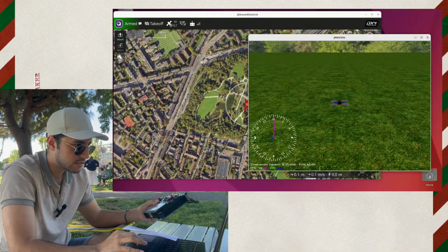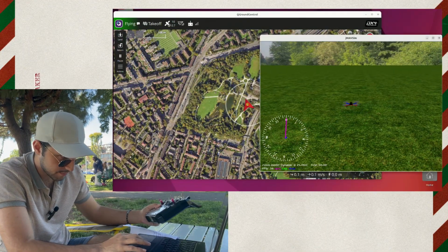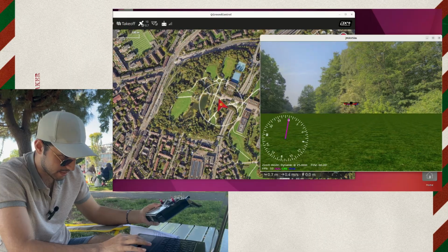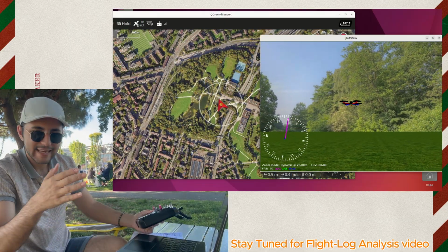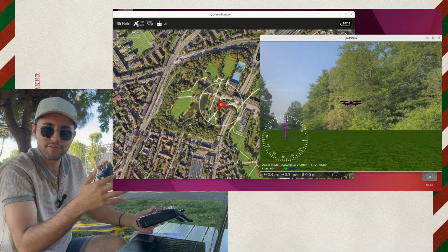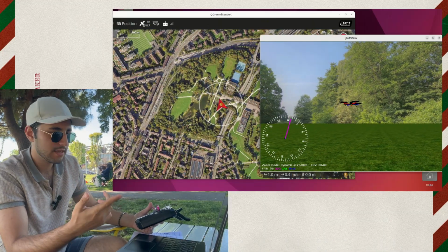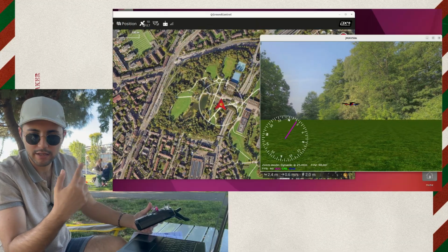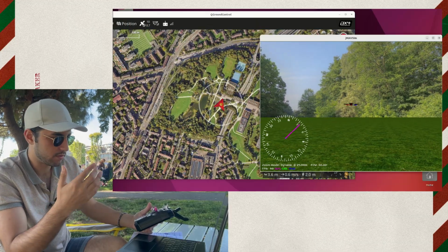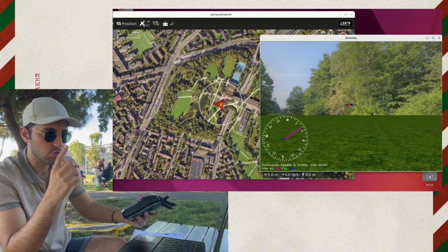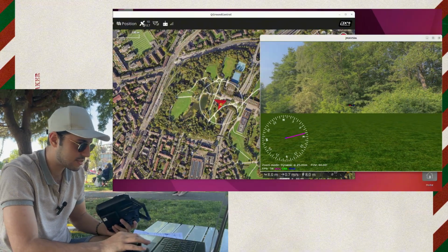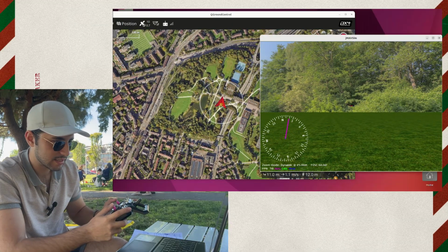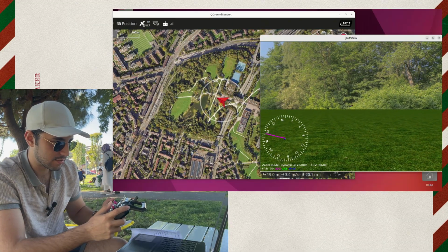Can we see the drone taking off in the simulation? Amazing. You see, when the drone was taking off from the simulation, it had some lag. It just came to the left. This means the motor frame should have some modifications. Maybe you can change the PID values or use a better Kalman filter to reduce the error. Now, when I touch this, it goes to position mode. You can see here it says position mode. So now I can basically run this.